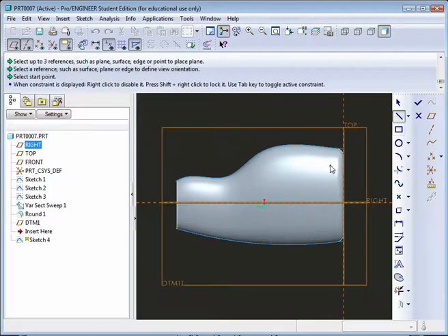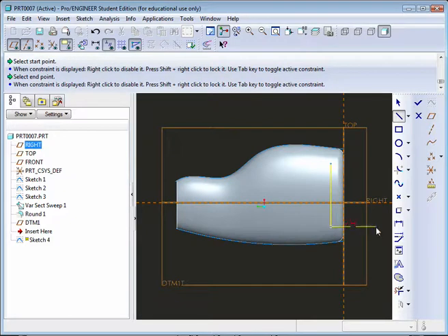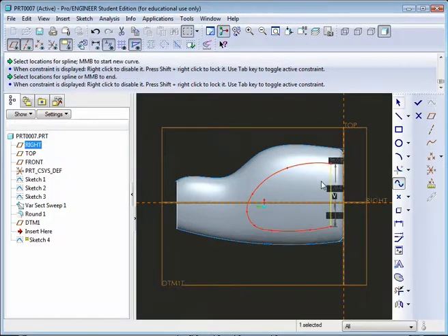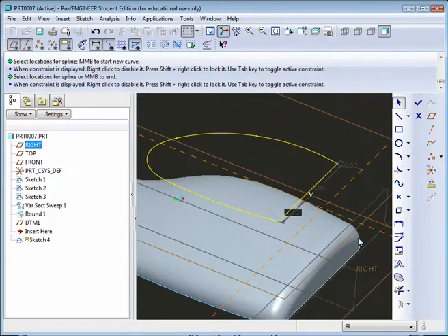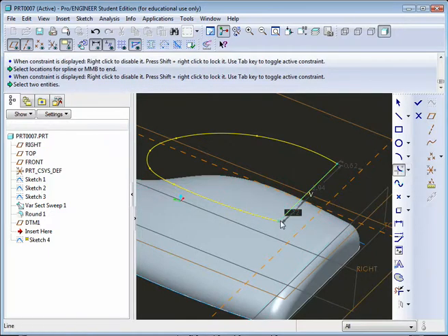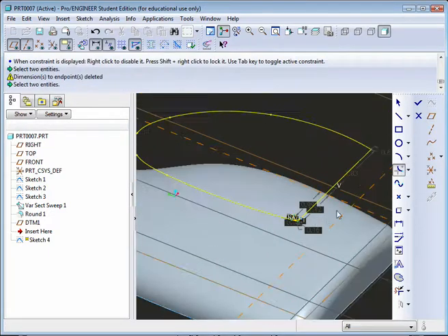And then we could draw our label recess. I'll just draw a straight line at the bottom and then take the spline tool and try and roughly follow the geometry that's there. Kind of make it look like it's following the outer edges a bit. You could always manipulate it by grabbing corners and points. Okay, then add some sketched fillets, or sketch blends, right here and here.